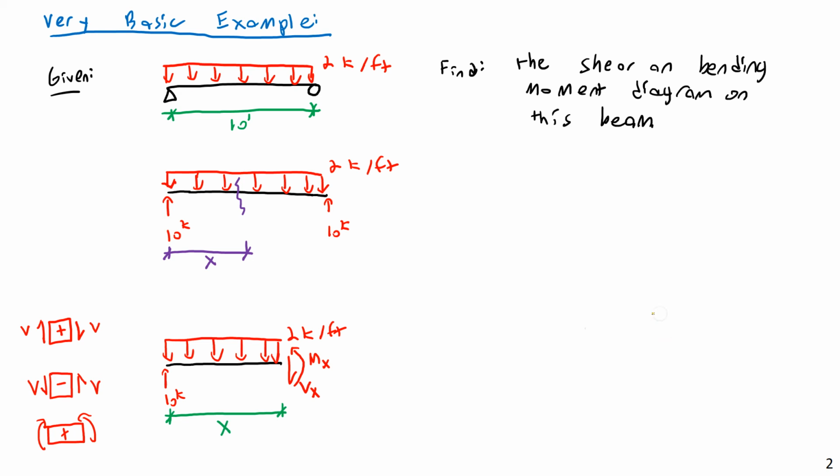So I'm going to show the equivalent point load on this thing. Now, we know that when solving for the forces on the edge of an element, we can use the equivalent point load method. And what that means is, again, we'll replace this distributed load with a point load that is the same total magnitude and positioned at the centroid of this distributed load. So what is the equivalent of this?